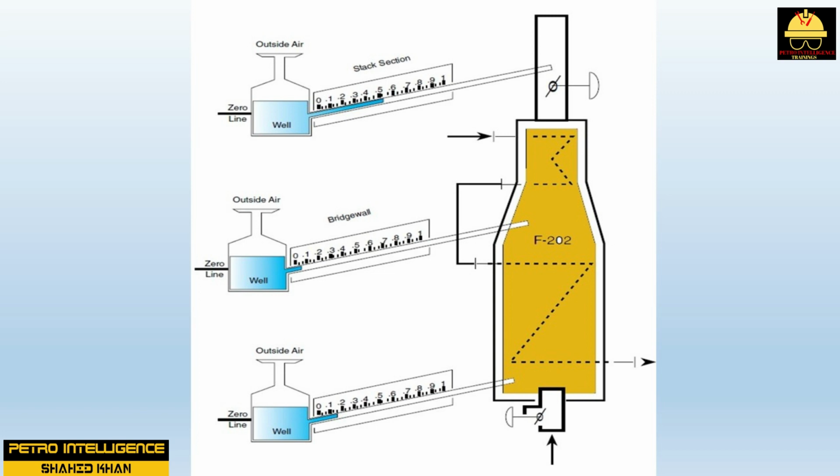When excess air is increased to the burner through the primary and secondary air registers, a temperature shift occurs as heat is moved away from the burners. Higher temperatures are found in the upper section of the firebox due to the reduced heat transfer in the lower section of the firebox. Temperatures in the convection section and stack will also rise significantly. This will reduce the amount of heat available for heating the hot oil, and more fuel will be burned in order to maintain process specifications.